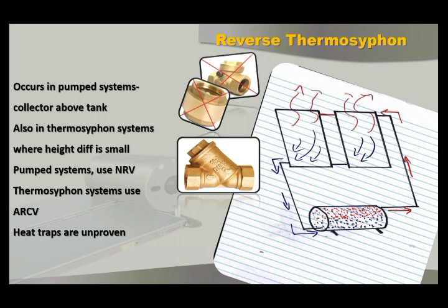Flush it out regularly, open it, inspect it, look at it. And if that happens to be on a 38-degree summer's day, you do not want to be draining that geyser in order to get to the valve, because you're going to burn yourself, you're going to burn everybody that's helping you, you're going to melt the geyser tray. So that's why it's got to be installed with 2 shutoffs either side.